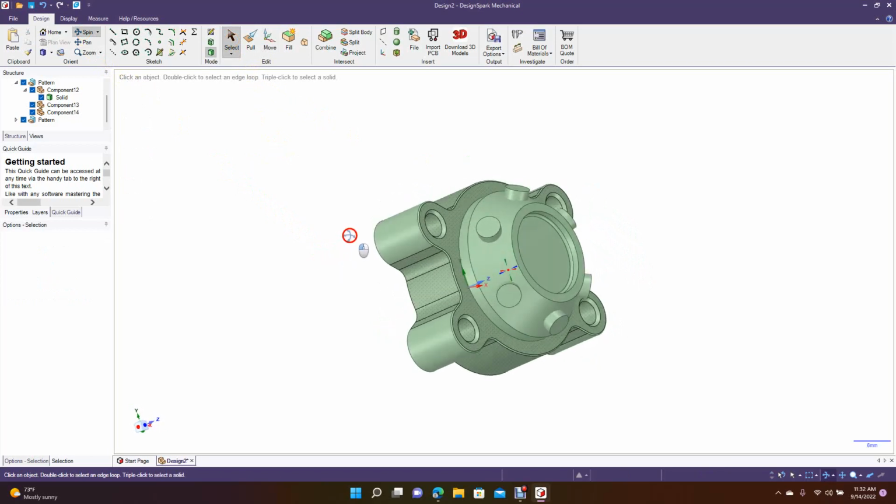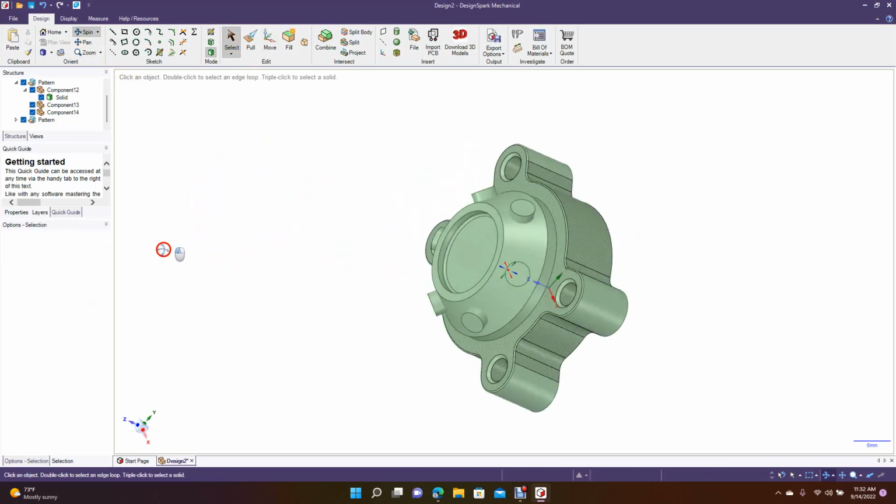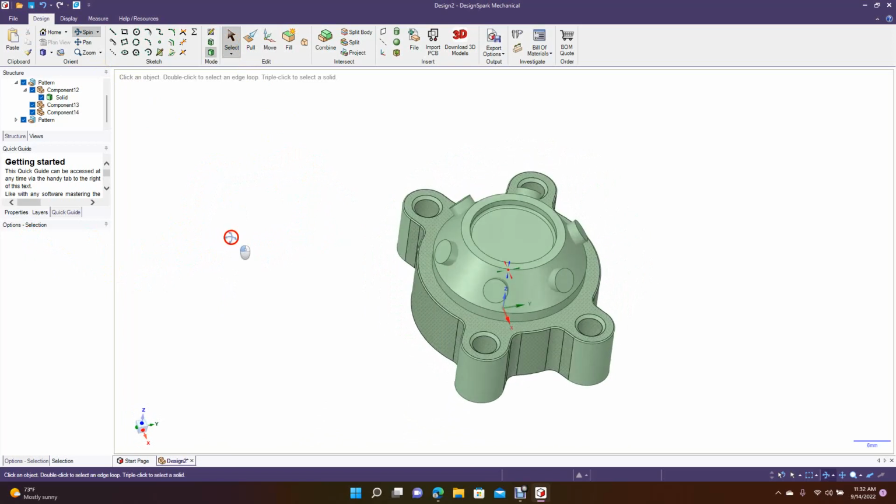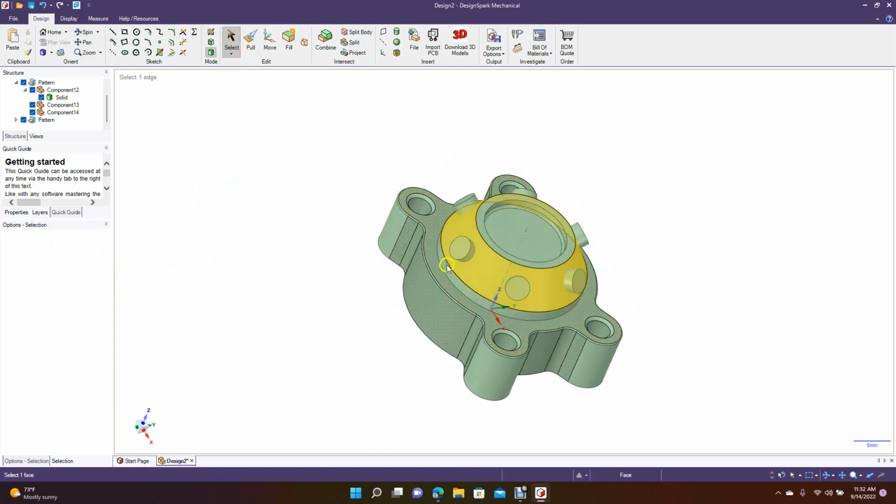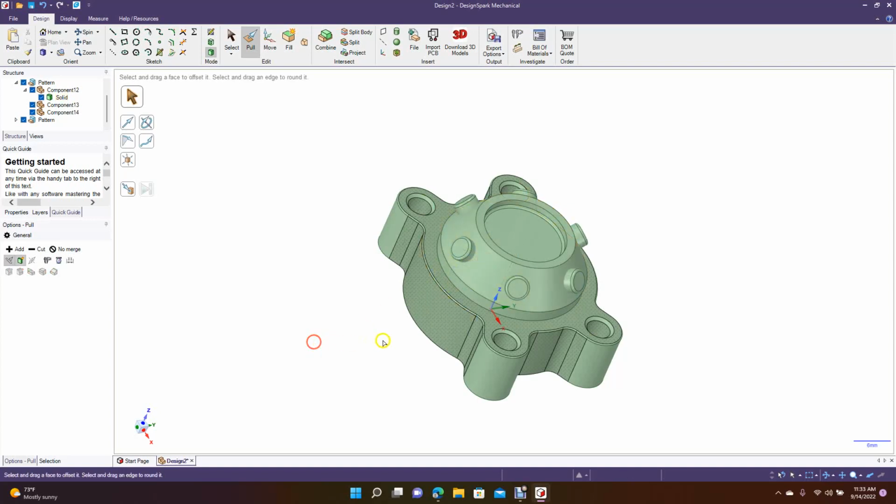Okay, so now we have this piece here. Kind of a funky cap. Now the only other thing I want to do to this is I want to add fillets to here. So just like this part down here, we're going to go ahead and create a fillet on this one here, which is going to do all of them. I don't know if I want to make these balls. They look kind of cool as just little round balls. So maybe I might make that. Let's just not do that. Let's just make them like this. So 0.35.